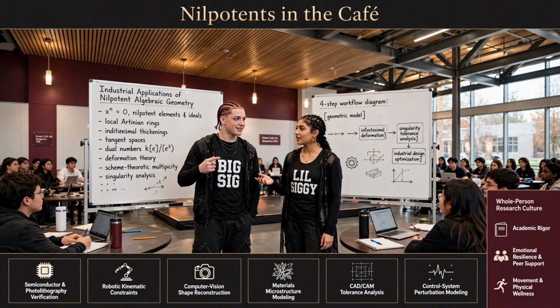Standard numerical methods handle simple intersections fine. Two spheres intersecting. Easy. But numerical solvers fail catastrophically near geometric singularities. What does a geometric singularity actually look like in CAD? Imagine a curve that bends around and perfectly kisses itself, creating a cusp or a self-intersection. Or imagine two undulating surfaces that don't slice through each other cleanly, but share a high-order contact point. They are perfectly tangent, grazing each other along a microscopic twisting edge.